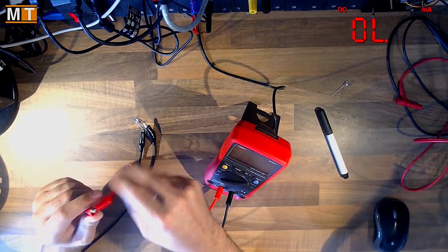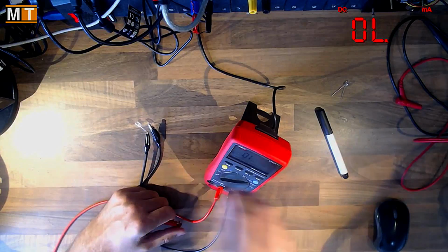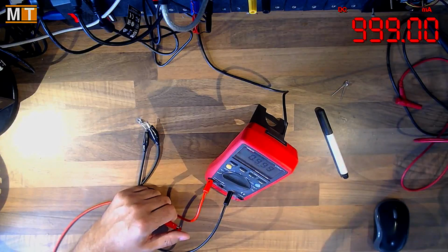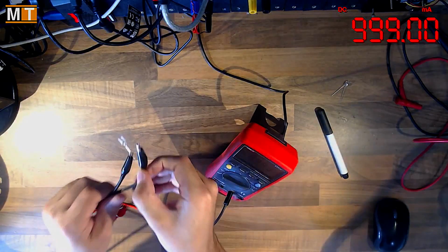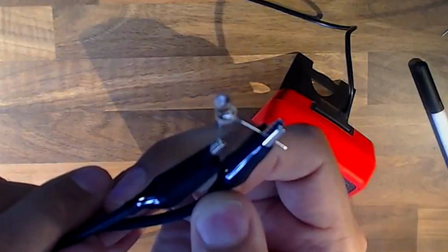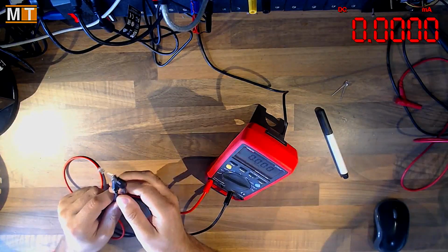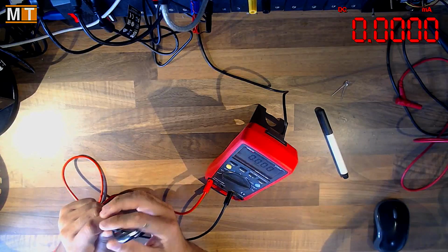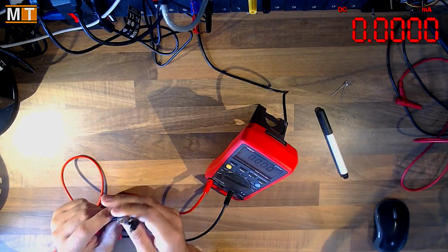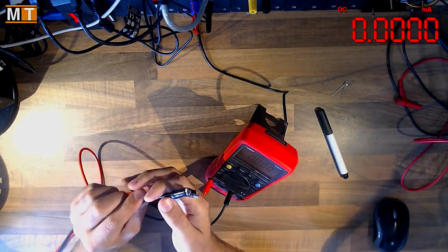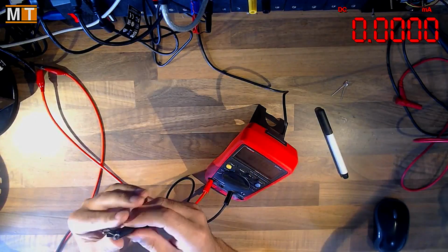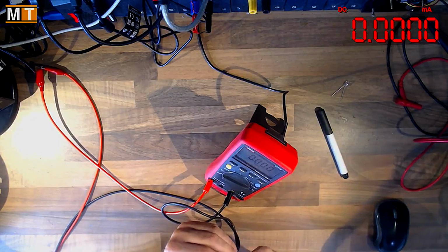Oh, nice. Smoking. Overload on the ammeter. Let's switch that to full amps mode. We have smoke. Oh, that smells good. Let's bring this a bit closer, see if you can see a slight red glow going in it. And it's blown. Nice. That's what happens if you power your LED directly from 5 volts without any limit on the current. The 12 volt supply just blew it instantly. The 5 volt supply, it just got hotter and hotter and smoked and glowed. And that was quite beautiful, actually. There we go. Casualty number 2.